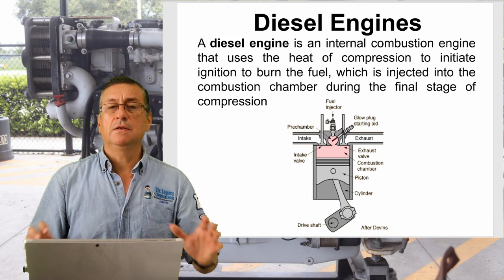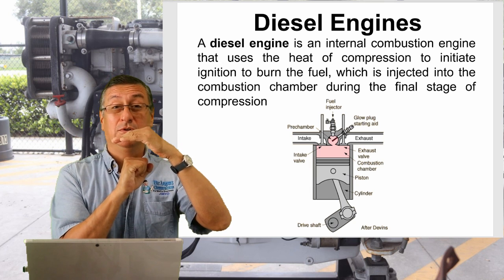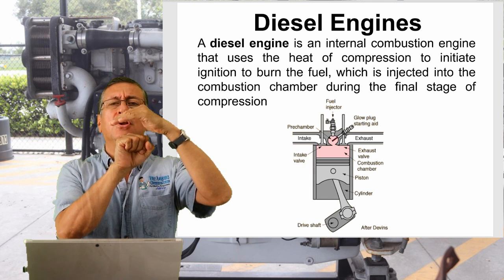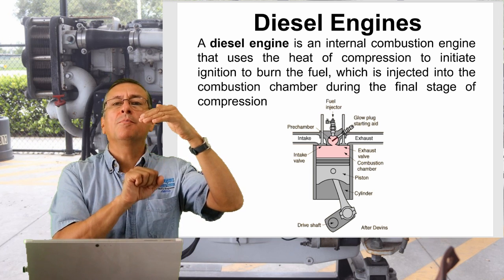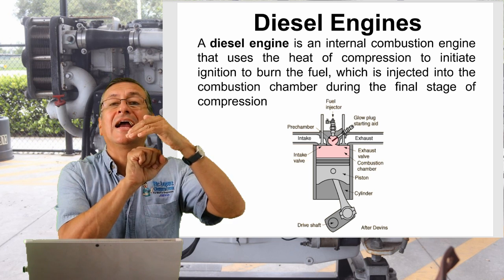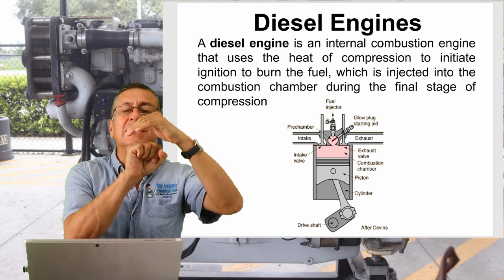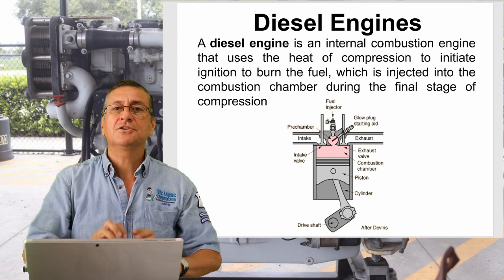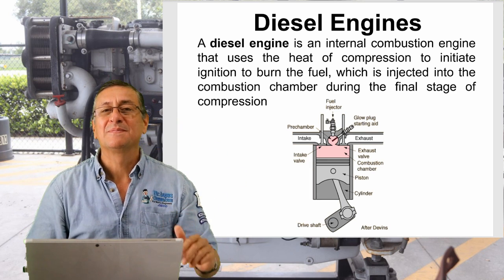In a gasoline engine, when the piston is at the maximum point of compression, or top dead center, with the valves closed, the engine compresses the mixture of air and gasoline. When the mixture is fully compressed, the spark plug produces a small spark, and the spark ignites the fuel and sends the piston down and starts the cycle.